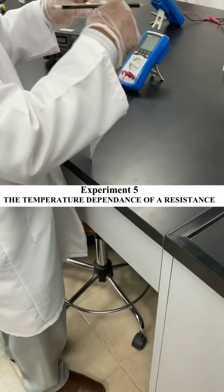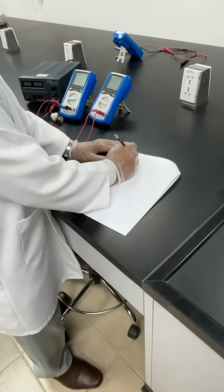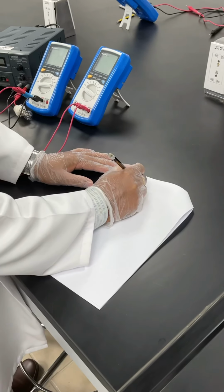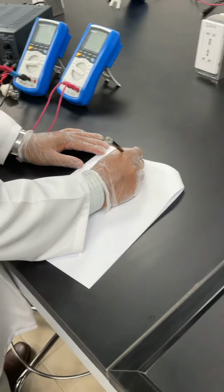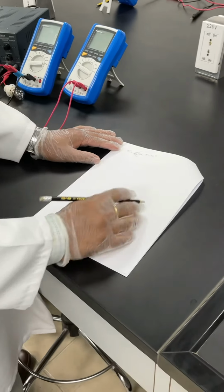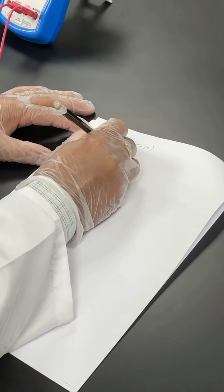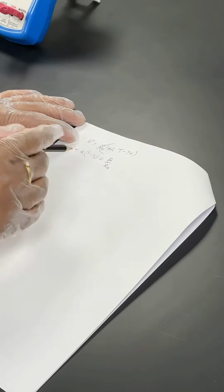The time is not enough, therefore I reduced it into one part. You are going to get the operating temperature. This formula will be given to you: 1 plus alpha (T minus T0) is equal to R by R0. R is the resistance at the high temperature, R0 is the resistance at the low temperature. T is the high temperature, T0 the low temperature.